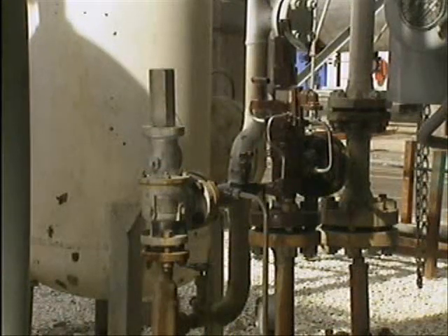Pilot-actuated relief valves are often used on gas and steam systems that also use safety valves. In such cases, the pilot-actuated relief valves are set to open at lower system pressures than the safety valves are. This arrangement saves wear and tear on the safety valves and prevents costly shutdowns that would be required for safety